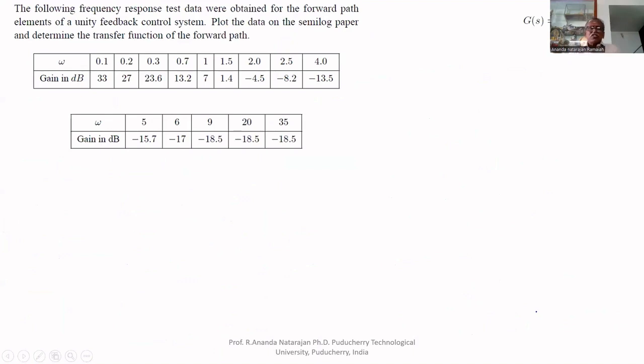Suppose you are given an instrument, it may be an amplifier or some other instrument. For that, you are required to find the transfer function by experimental way. How can we find it? We have to find the frequency response for this. This is the magnitude response.